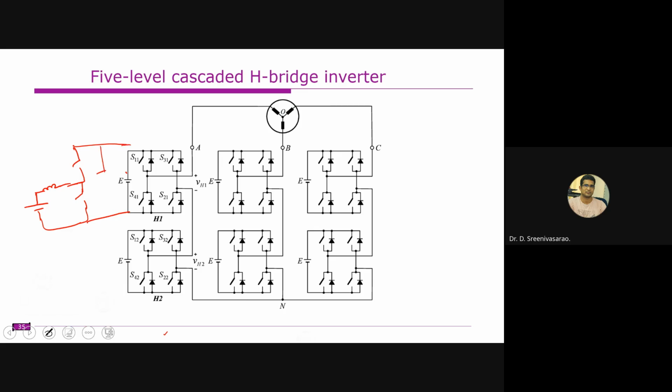And we normally have some capacitor. This is the bidirectional boost rectifier. So this is one switch, and this is another switch. Depending on the mode of operation, it will be in buck mode or boost mode. Normally, this voltage will be higher compared to the battery voltage. So this is the boost operation, and this will be the buck operation. This will be on during the boost time, and this will be on during the buck time. Likewise, it will operate. This is one more circuit. Or sometimes we use another circuit, if you require some isolation. In that case, we may prefer the dual active bridge converters.